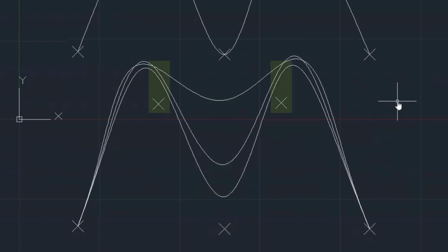But it's a different story with the top points. This is very important to understand, as tolerance doesn't mean that every point will be at 2000 units of distance away from the spline, but will have the ability to go up to that distance. So the line would have to apply less distance to the top points to accommodate a 2000 tolerance from the bottom point. Since if the line went 2000 units of distance above the top points, there would be far more than 2000 units to the bottom point, which is the limit of our tolerance.